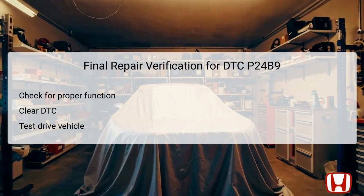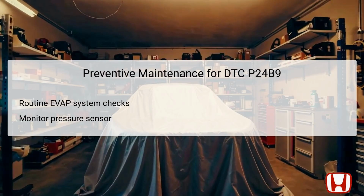Following this, a test drive is often conducted to observe the vehicle under real-world conditions, ensuring that no further anomalies arise and that the check engine light does not reappear. This verification is critical for confirming that the repairs have effectively resolved the issues without introducing new problems in the emission system. To prevent recurrence of DTC P24B9, regular preventive maintenance of the EVAP system is recommended.